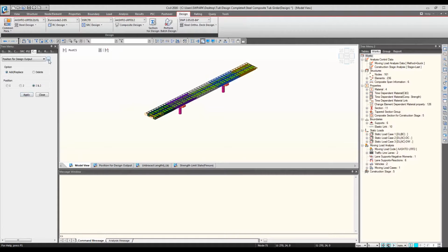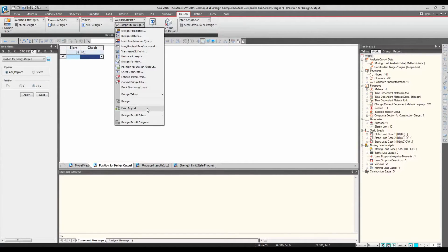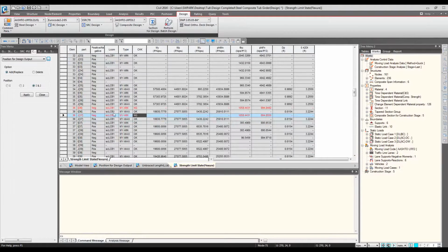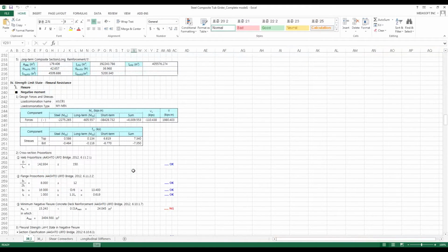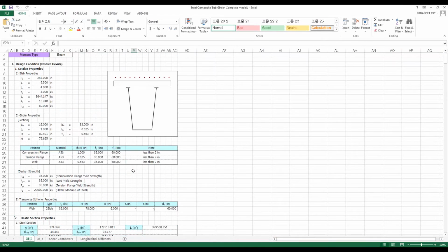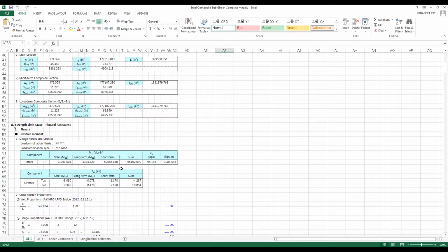And once you click the dot box on here, you can see the table information. And then you can click the Excel report button on here. You can see the Excel report. But to shorten our time, I already made my Excel report on here. And there were some problems with element 36, as you can see on here. So if you want to see more specific information, this one is the element 36 report. All the information is punched on here once you click the extract Excel report,